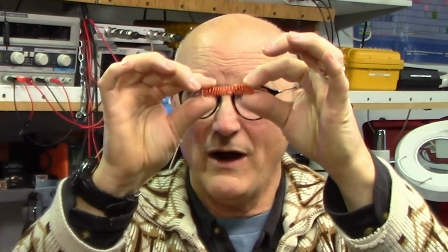If you choose to use an inductor with a larger inductive reactance, then it will require a larger change in inductance to affect a relatively small change in tuned frequency. While a toroidal inductor would work, it gives us no adjustability. On the other hand, if we use an air core coil, then we don't want to wind it close wound.